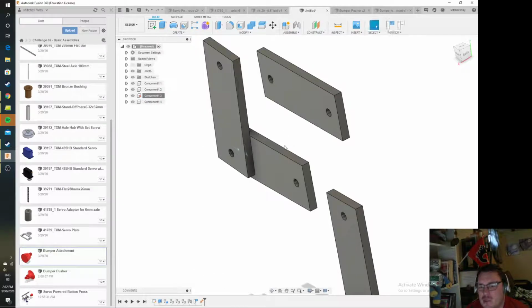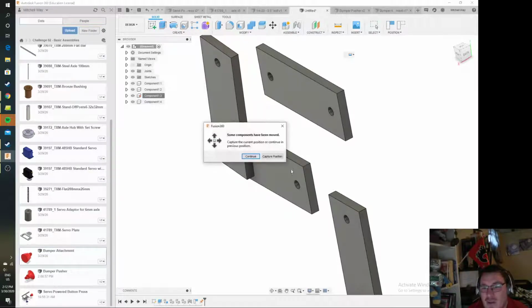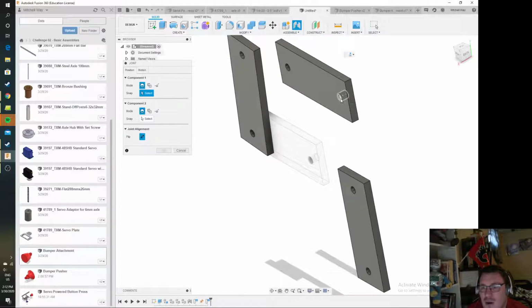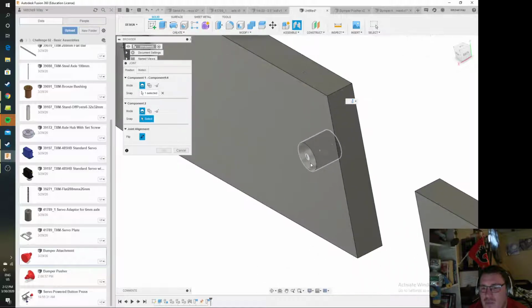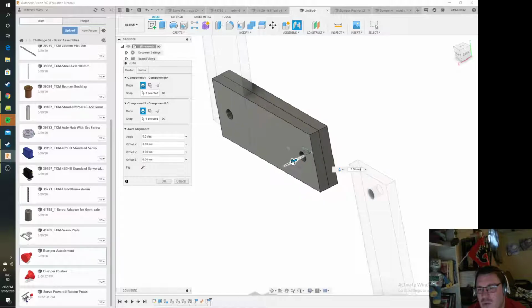Now, there's a few other pieces you need to know here. We just grounded something so it can't move. We've got the rotational axis, or rotational motion here, and the last thing we're going to do is play with another couple of joints here. I'm very quickly just going to grab another part here, cylinder to cylinder, and you'll notice they try to connect them together. That's awesome. I'm going to offset it by 5 millimeters again. I'm going to press OK.